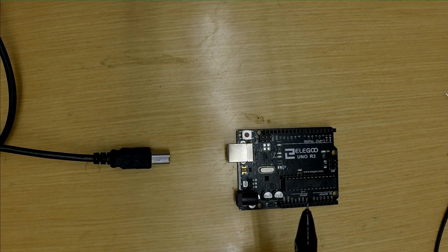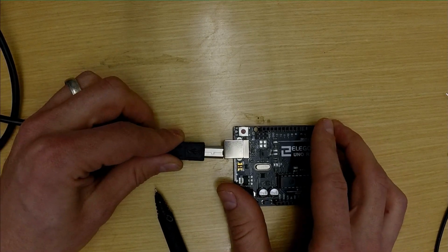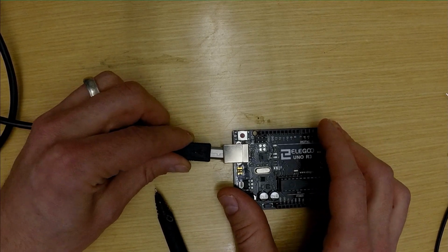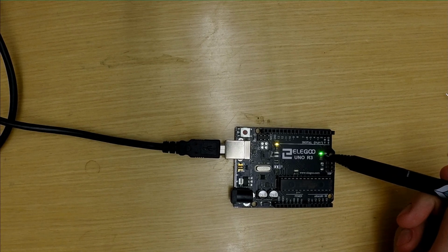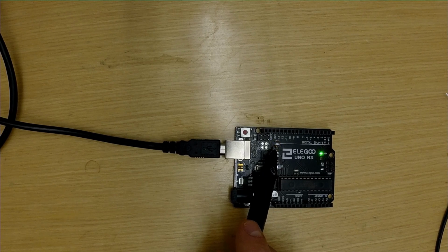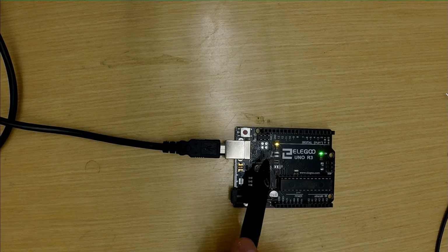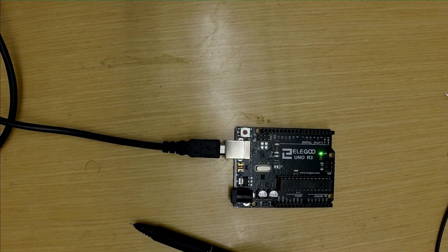So with that, what we can do is plug this in and we'll show you what it looks like when it powers up. To power up the Arduino, all we have to do is plug it into USB, and it's going to pull the power it needs over the USB port. And so we get a power LED that will turn on once we have that, and our pin 13 LED is blinking. Now this doesn't necessarily happen every single time you plug in the Arduino. It depends on what code has been loaded onto the Arduino, because as soon as it gets power, it's just going to start running whatever code is in its memory.